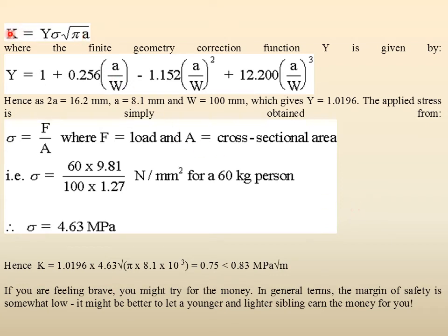So from this same equation, either use K1C as the material property and find the sigma C or sigma F at which the material will fail, and then compare your actual sigma with this sigma F. If your actual sigma is less than that, you are okay. Or find the sigma, put these values here, and find the stress intensity K1 in the current situation, and then compare this K1 with the given K1C, right? So this is it. So you have solved it, you have done it.